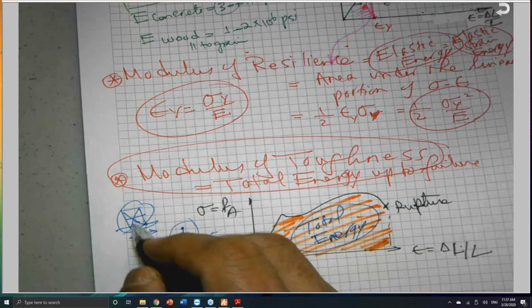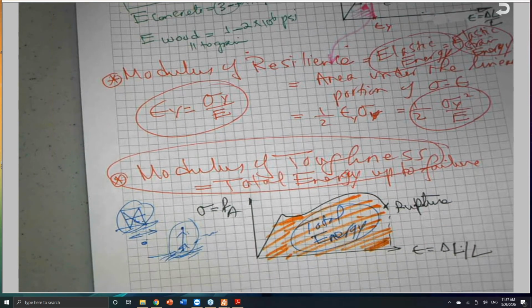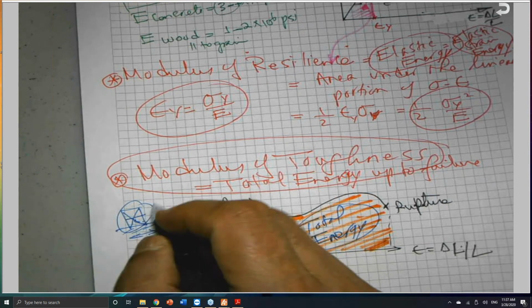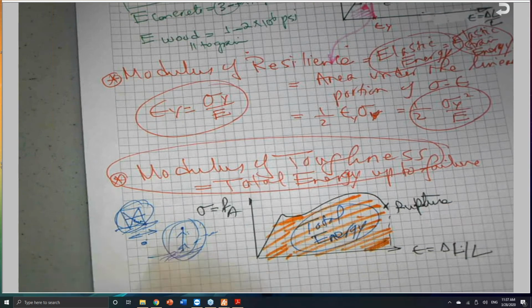Because all our intent from seismic design is to save lives, not to maintain the structure. The structure may deform a little bit. If I have a bridge, I don't want the bridge to collapse completely and fall down into the river or valley. If the bridge suffers minor damage, some cracks here and there, I have no problem with that, and the code will accept that. But I don't want a structural failure where the building collapses completely, like Mr. Mansour here, when somebody hits it from the side with a big hit because it is not able to absorb it.